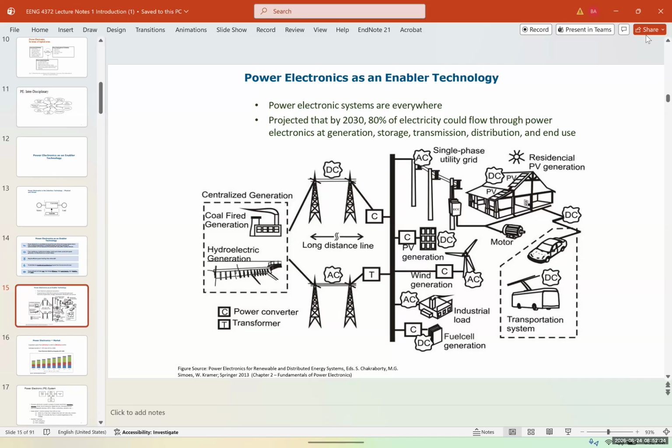In a microgrid or a smart grid, the difference, by the way, between a smart grid and a traditional grid, is that a traditional grid is a one-way system. You have a power plant and you have a consumer, and there's no communication between the power producer and the consumer. And for a power system, it's an on-demand system. You cannot store the power. So whatever is generated must be consumed at the same time.